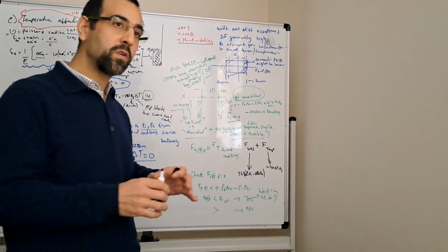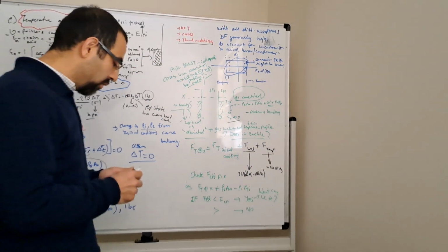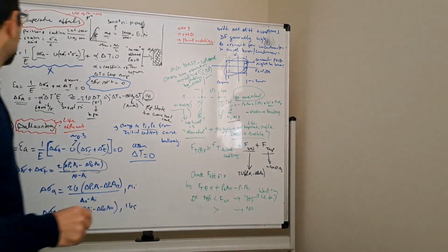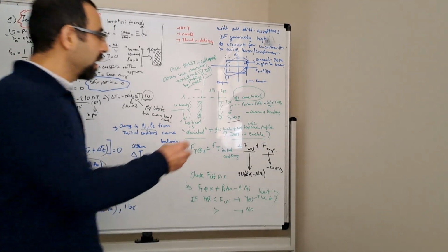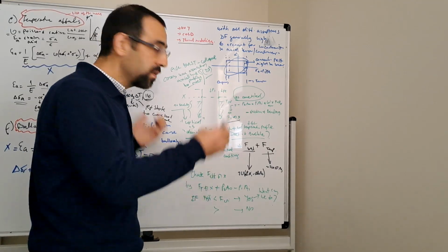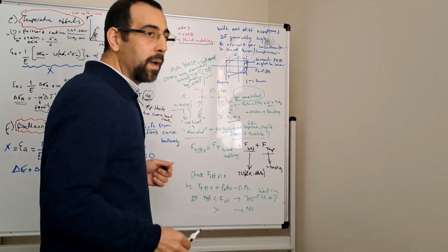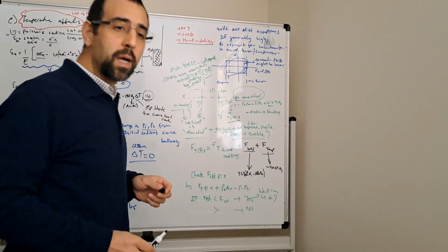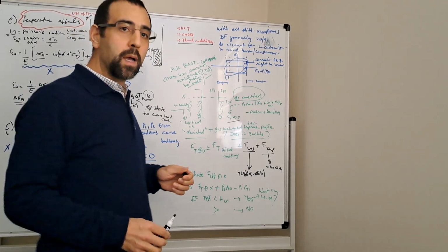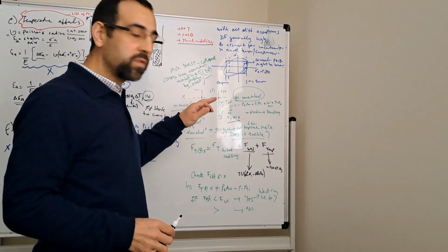Okay, the ballooning force from the initial stage, and then also you have the temperature-related forces, right, which we covered in this part. So in the kick stage, what happens is you take a 10 barrel, 20 barrel gain, whatever, and then you will have some kind of a temperature, kind of a geothermal, maybe a bit warmer than the geothermal.